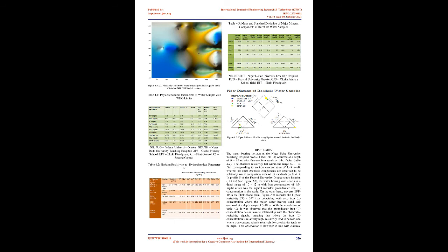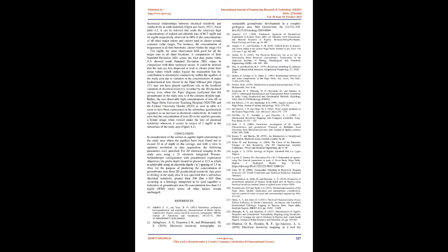The major sand body occurred at depth less than 10 m, corresponding to the 20 m electrode position with maximum resistivity of 169 Ωm. To the right of the section, resistivity values seem to be spurious with values as low as 2.1 Ωm, 3.4 Ωm, 9.1 Ωm, 39 Ωm and 64 Ωm, indicative of the presence of conductive fluids and/or layers with clay minerals.